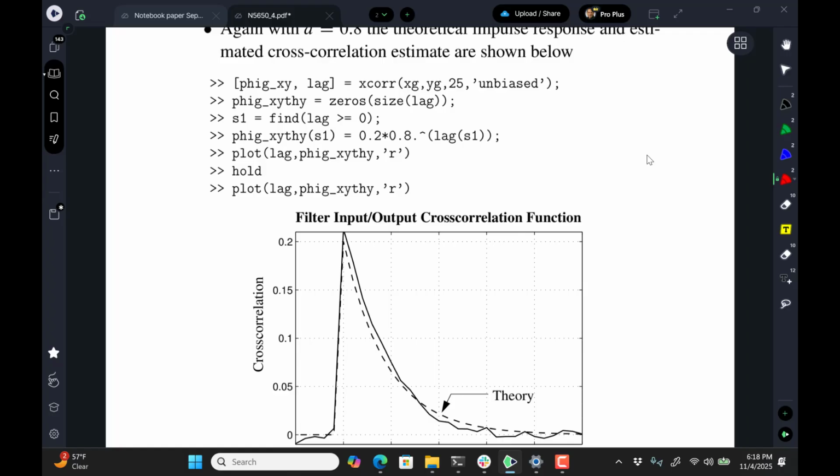So this, in control systems, is called system identification. You have a system, you'd like to identify what is in the black box. You know it's a linear system. You drive it with white noise, and then you record the noise at the output and correlate it with the noise at the input, a cross correlation, and then that can get you in the spectral domain what that cross spectrum is, and then inverse FFT that or whatever, and you get the impulse response. It's kind of cool if you're into system identification, which shows up in applications more than just controls. It's trying to learn about something.